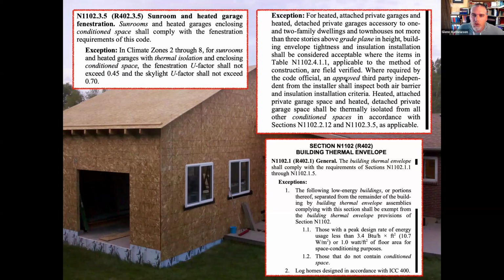And then the next one that just dropped down was a special thing for heated garages under air leakage. Here it's saying you don't have to do the blower door test like you would for the rest of the dwelling. So let's think about this, right? Thermal envelope, nope, you still have to do it. Fenestration, we're going to let you be a little bit less good. And air leakage, we're not going to make you test it to the air changes per hour. And why? Because right there, a garage door.